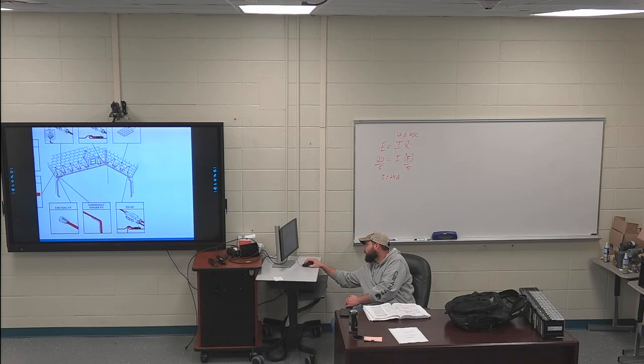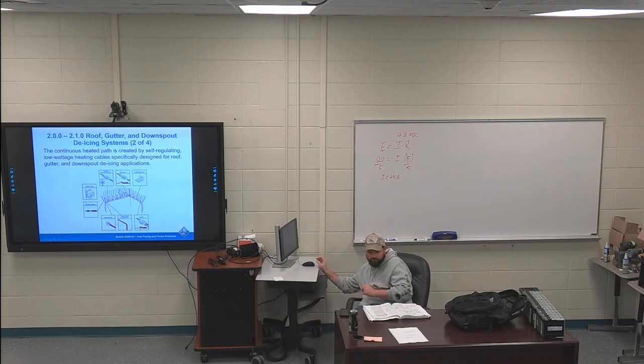And that's so the water will not go into it. I don't want water inside of this T-kit, where this stuff should be sealed off, but everybody knows water finds its way into stuff. But you can also see where they left drip loops down into here, so as stuff melts, water is right here rather than sitting on the cable or trying to get somewhere else. You're just putting drip loops where you want water to melt off to, and you don't want water to melt off into your different components.